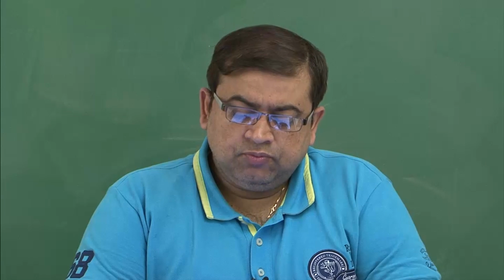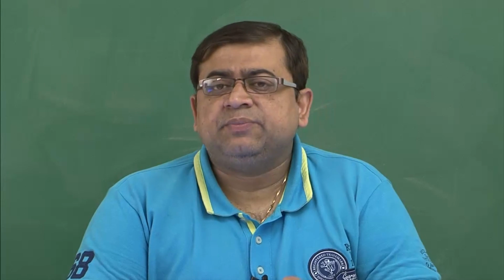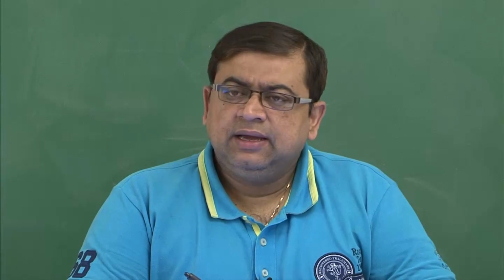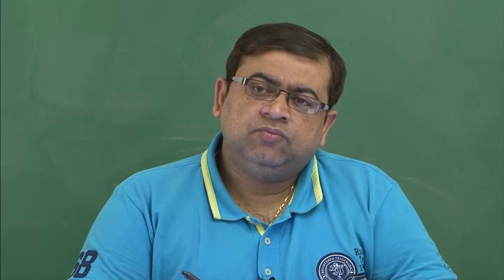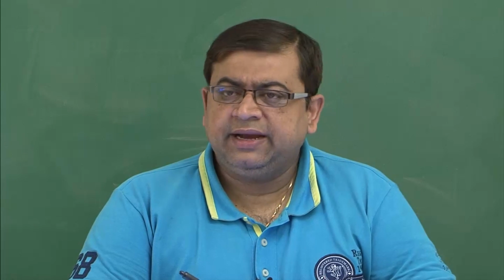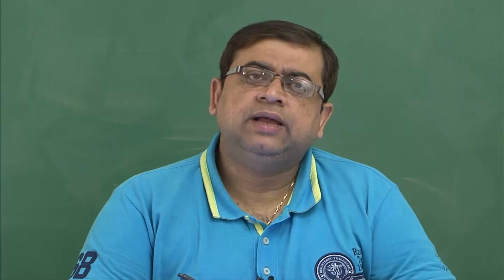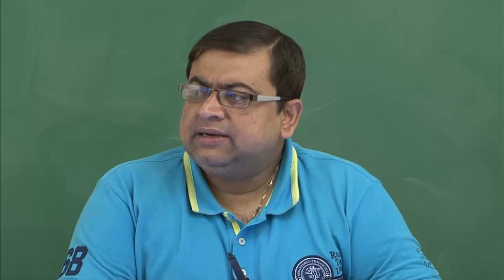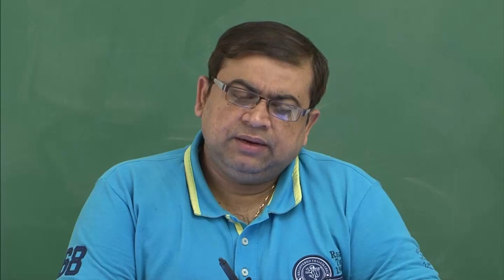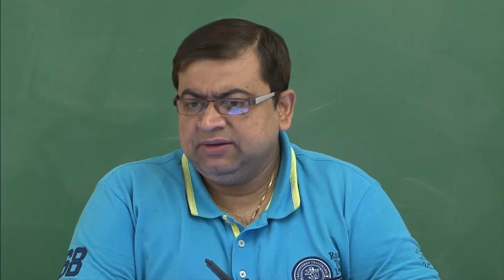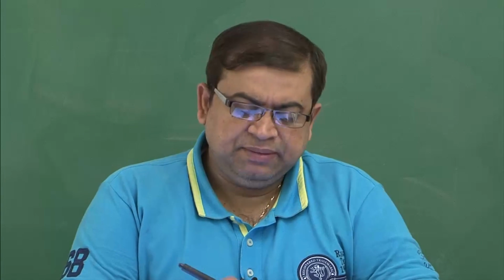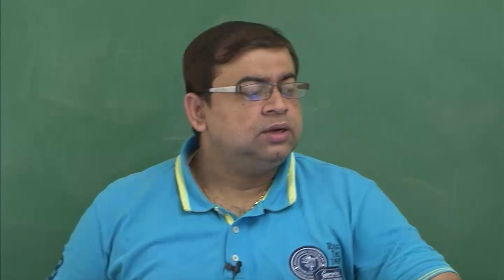So we will first look into the basic principles of laser machining, and then discuss a little bit of the physics of lasers, followed by what kind of material removal rates would exist in laser machining. We'll also look at some parametric studies of the different lasing processes and try to correlate the one dimensional heat transfer equation to see what the depth of melting temperature would be for different sizes of beams.